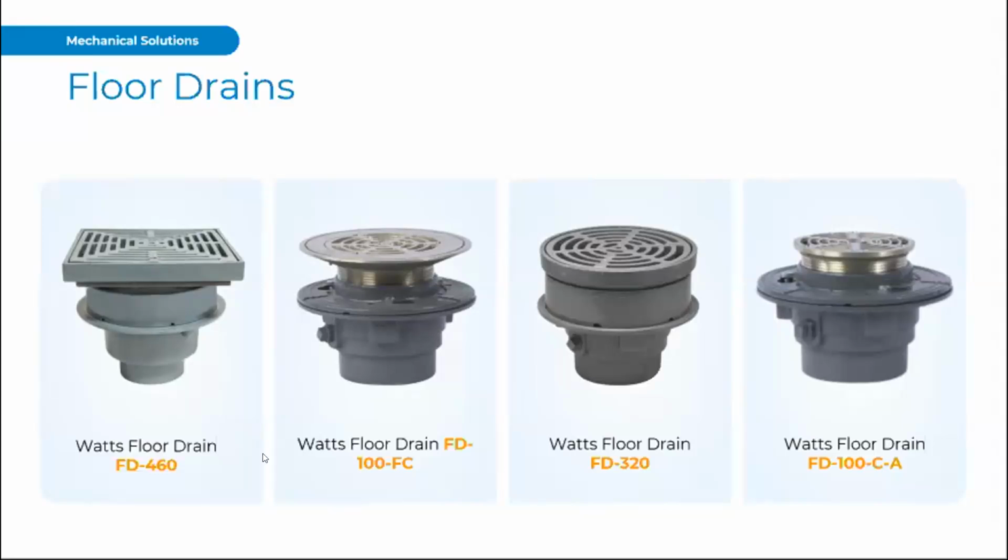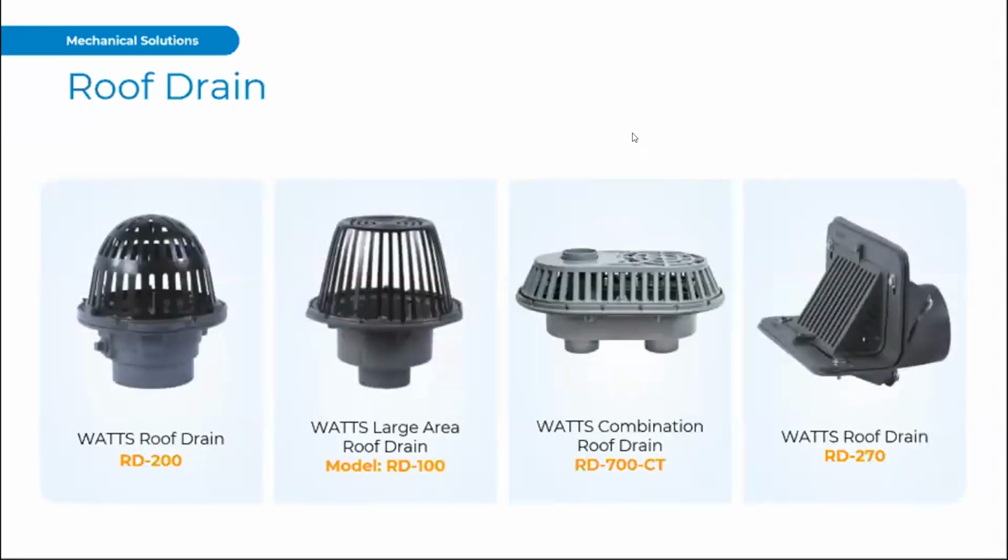Looking at more of our area drains, the 460 is a great option. There's the area drain for outdoor parking areas as well, which is an all aluminum body for Canadian applications. All of these are in that template, so you'd be able to select the ones that meet your master and make sure that you have things like your 320 included in your standard, which would be your mechanical room drain, 8-inch heavy duty top assembly, long lasting, and available with funnels in case you need the funnel floor drains.